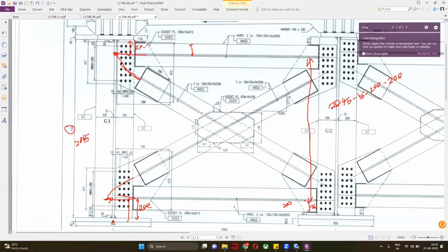No, this gusset plate size we do not need to see, sir. The gusset plate is a part of your connection design. Why do we require the gusset plate right now? This just comes in our design calculation, when we do the connection design. And these are also only shear connections, so we do not require any bending moment. Shear connections are very easy to design and do not require very complex calculation.